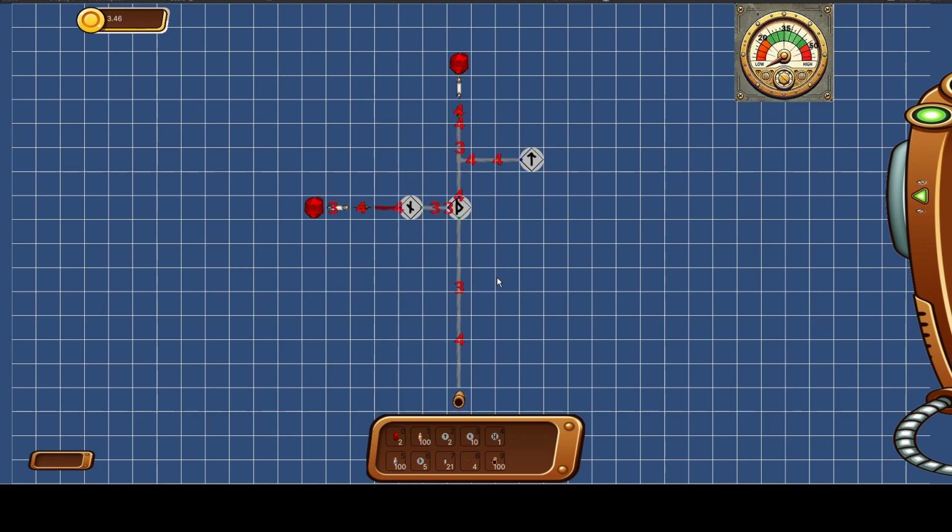If you know how many watts it can manage to dissipate, you can take the wattage and use the square root with the power formula that I mentioned before. I squared times R, take the square root of that, and you'll get your I. I think it's something like that.